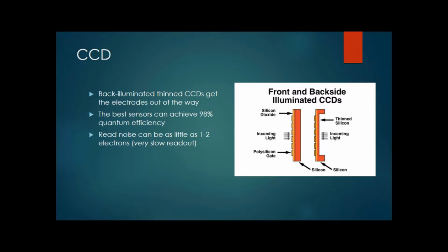Really super high performance. Another disadvantage of typical back-illuminated sensors is they have to be cooled a lot more to have low dark current. So the cameras tend to be also very expensive, not just the sensors.